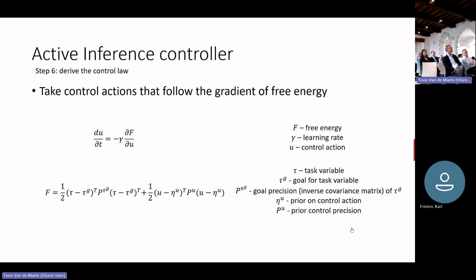We will have the force coming inside this in the coming slides. Actually, U is the control input that is going into the system. So just treat this slide as independent from everything I told you before, and let's not confuse it with the force there. It's just that the control input is U, and in the spring mass damper case, that is the force. So you're trying to minimize the effort or the force that you're going to give into the spring mass damper system if you use this in the free energy.